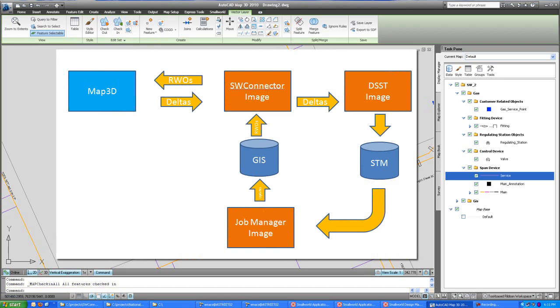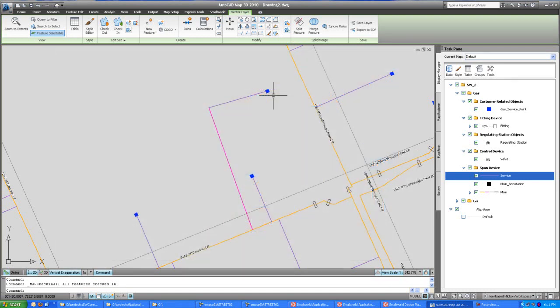The changes that I've sent back to Smallworld have not been made directly against the main service and service point tables. The changes are held in a job manager database. This short transaction database allows me to record the transactions as XML objects, which can then be played into the database by an operator, allowing them to visually inspect the changes that are being made and, if necessary, make changes on the fly if values are incorrect. The next part of this demonstration transfers over to a Smallworld session.